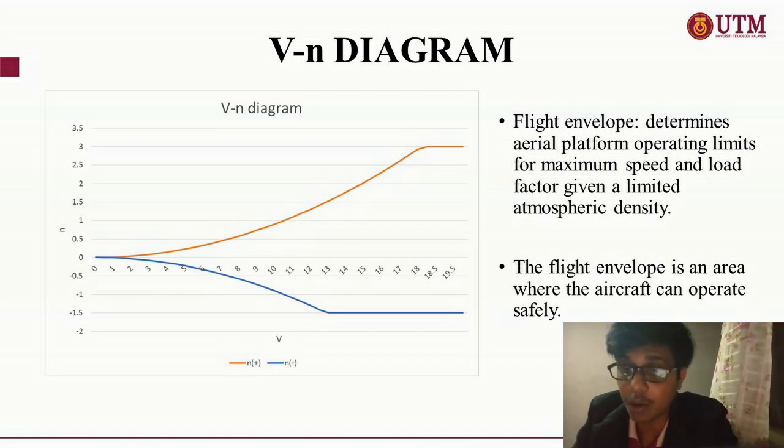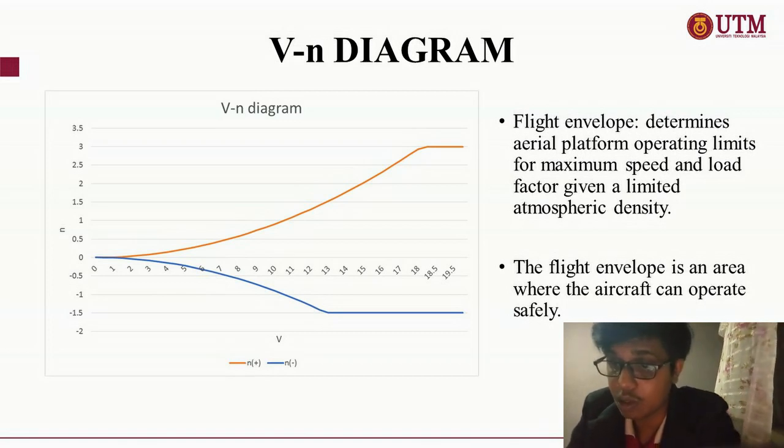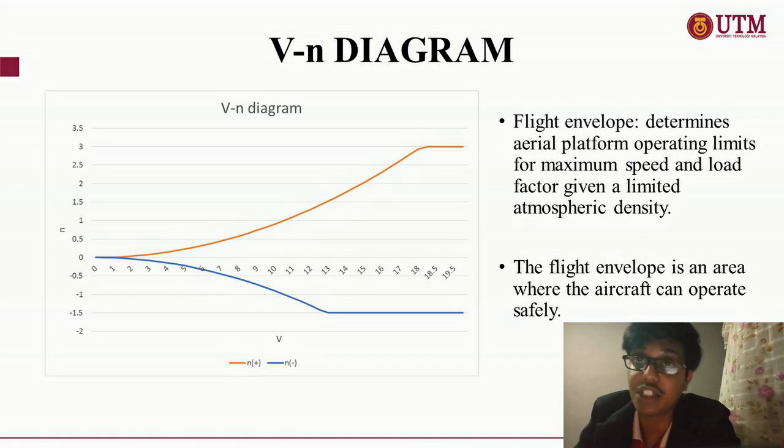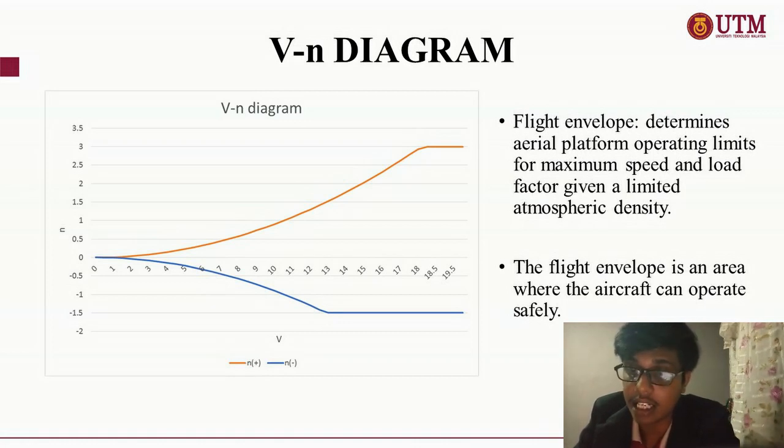If you look at one of the observations we make, it looks like parabolic curves called the stall line branch out of the origin on either side. Each curve represents a particular altitude. The graph gives us the stall speed, the never exceed speed, and the limit load factors for a particular altitude. The stall speed for 1G flight in this case is 200 knots up to that altitude.